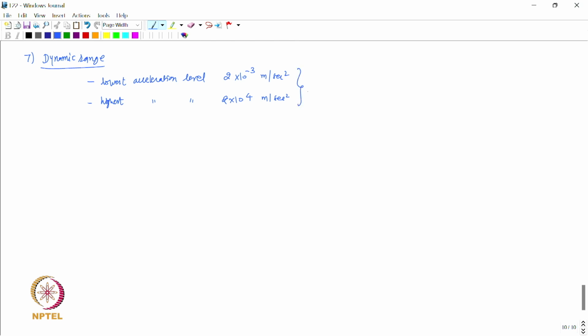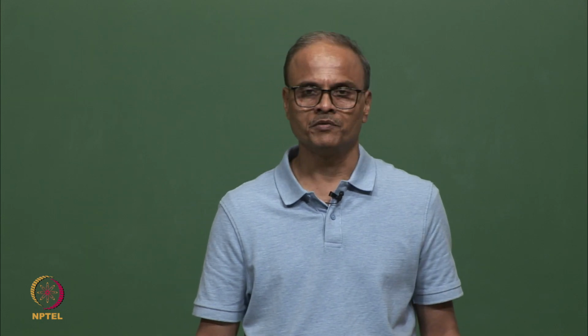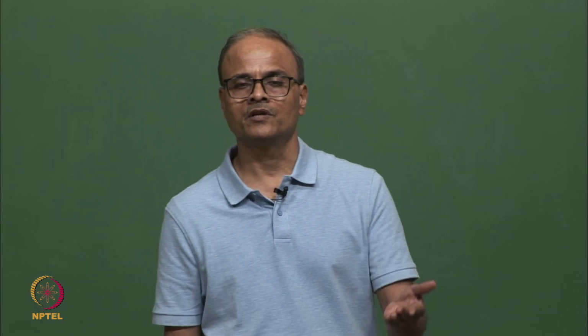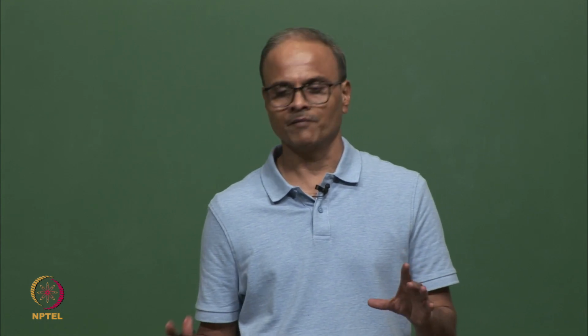This corresponds to a dynamic range of around 140 decibels, which is a pretty high dynamic range. And therefore, the accelerometer that is chosen should be such that the accelerations encountered in practice, which we want to measure, fall within this dynamic range.